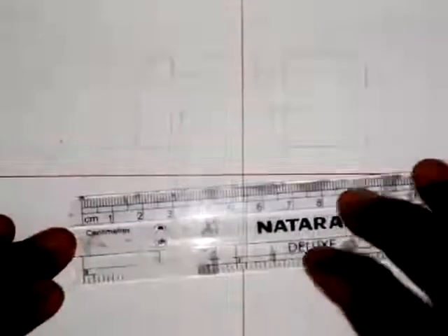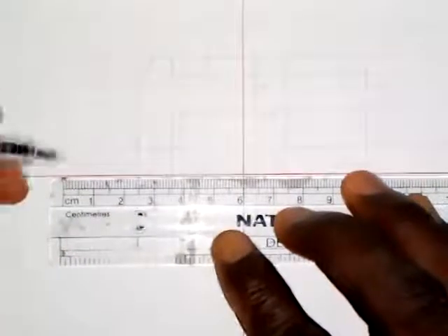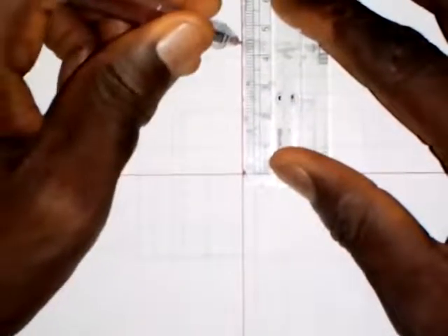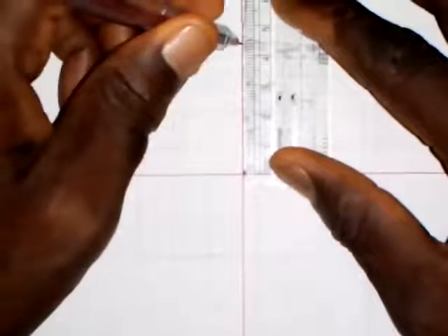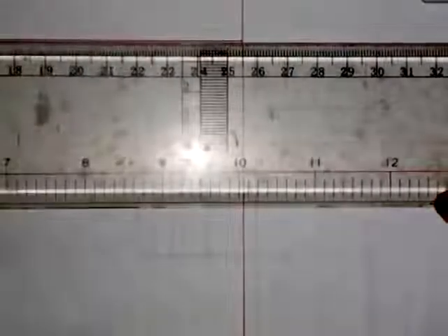Okay, so we are starting with the plan. For the plan, we have a rectangle of length 60 millimeters. So you take a measurement of 60 millimeters from here, and the width is 44 millimeters. So we first complete that. This is 44 millimeters. So here we have to draw a horizontal line like this, and then we draw a vertical line. So draw a vertical line from here to here.